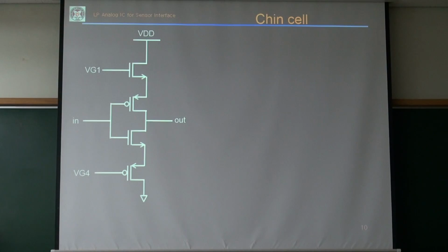Yeah, let's revisit this cell. In this cell, there is an inverter, and then I have an NMOS source follower at the VDD side, and a PMOS source follower at the VSS side. So the inverter supply voltage is limited on both sides, right?